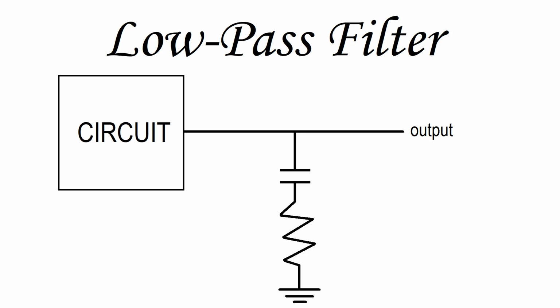Again, it doesn't matter which side of the capacitor the resistor is on. Either way, it is restricting the flow of current in that direction. This will result in less high frequencies being filtered out. If you want to control the amount of high frequencies being filtered out with a knob, you can use a potentiometer as a variable resistor in place of a fixed resistor. This will give you adjustable tone. This is the same way that a tone knob on a guitar is hooked up.